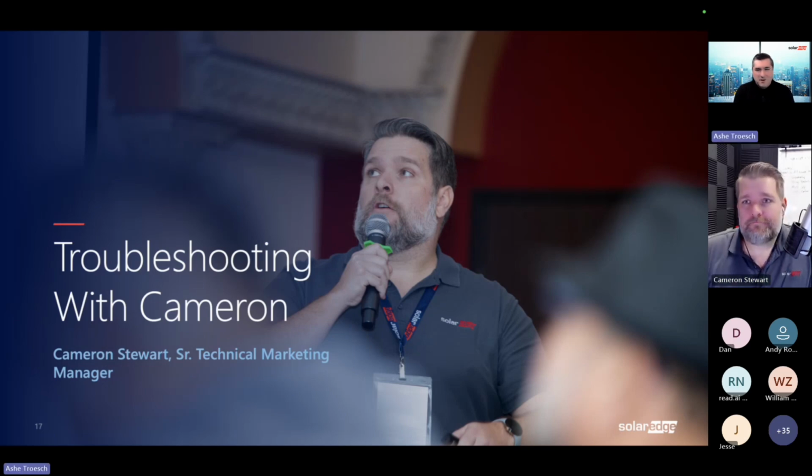Awesome. That makes it super simple. Looks like we had another question asking if the slides were based on the HD Wave or the Home Hub. To answer that question for you, everything in the presentation was based on the Home Hub, but all of the math that we used could be applied to the HD Wave as well. So you would just take the sizing of those HD Waves and multiply it by the 1.4 or the 1.5 to get that maximum system size. The only difference here is that the HD Wave doesn't support batteries, so you would never want to use the 200% with our HD Wave solar-only models.